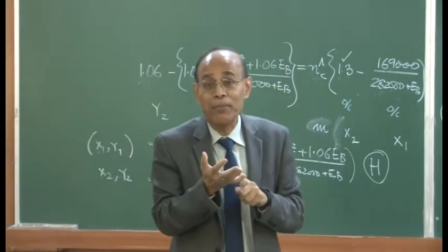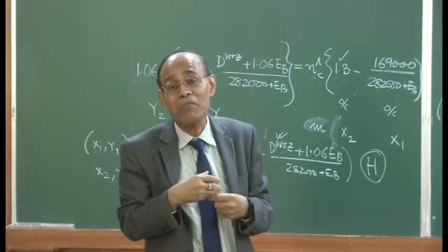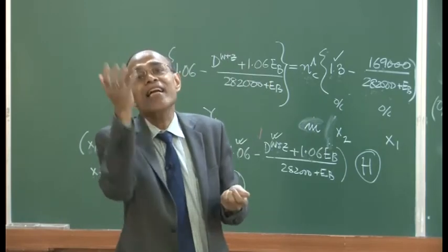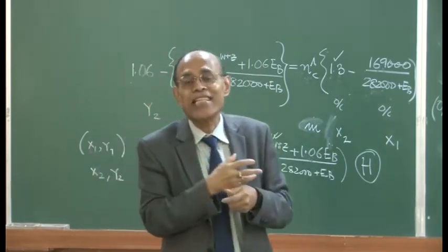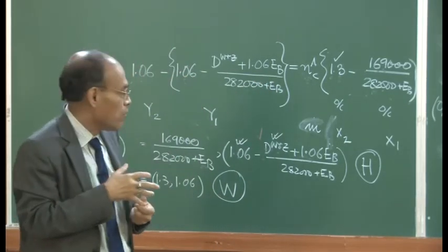Now for example, you have surface losses through the bottom segment, that could be another term. You could have metalloid reduction, you could have slag formation, you could have lime heating up. You have to supply the calcination heat, and there are so many terms which can get added up to the demand terms itself. Okay?